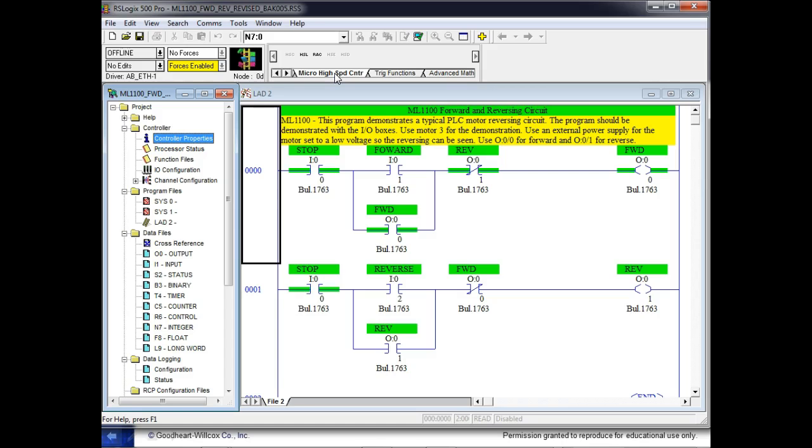And these are called what? High-speed counters. So if you're going to run an encoder which senses the speed of a motor, then you're going to have a PLC that's got at least one high-speed counter in it. So you don't have a program instruction for a high-speed counter. You've got instructions to configure the high-speed counter, right? And also to get the information from the high-speed counter.